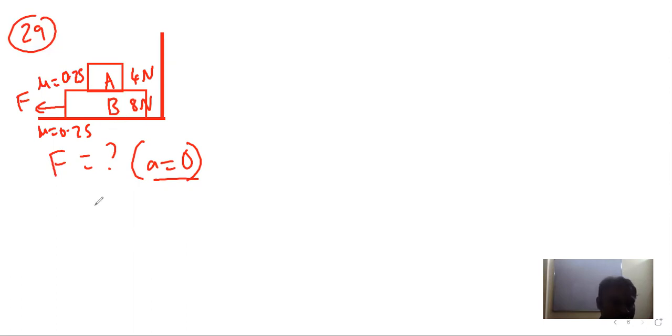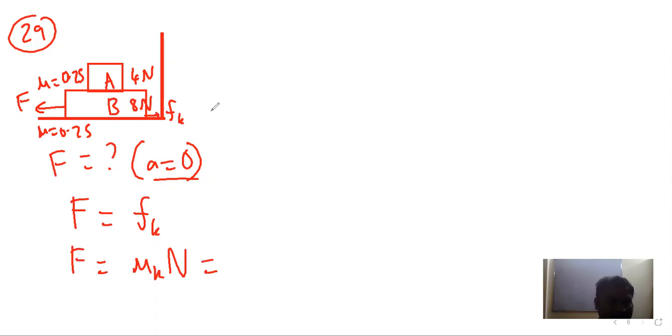So that means the applied force is equal to kinetic friction, because the applied force and kinetic friction act in opposite directions. So applied force is equal to mu k into N. So mu k in this case acts in the backward direction. Normal reaction here acts, which is (M plus m) into g on the lower block. Why?